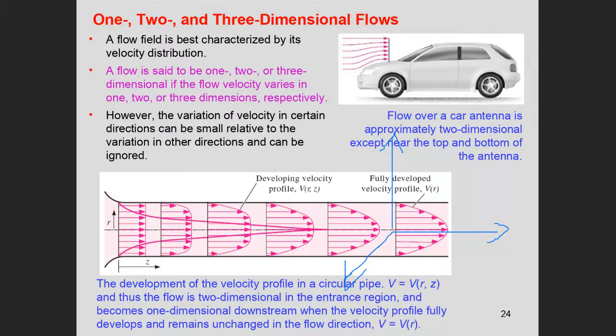Okay, but let us talk about X, Y, and Z. A fluid flow can be three-dimensional, but sometimes we say the variation along Z is not very significant, and we can ignore the Z direction and talk about two dimensions only. We can describe the fluid flow as an XY system only. But we can also go to the extreme and say the variation along Y is not important, and then the flow becomes one-dimensional, along the stream, the X direction. But generally speaking, any fluid flow is three-dimensional. Not three-dimensional, it's four-dimensional, because time comes in and characterizes the fluid as either steady or unsteady.